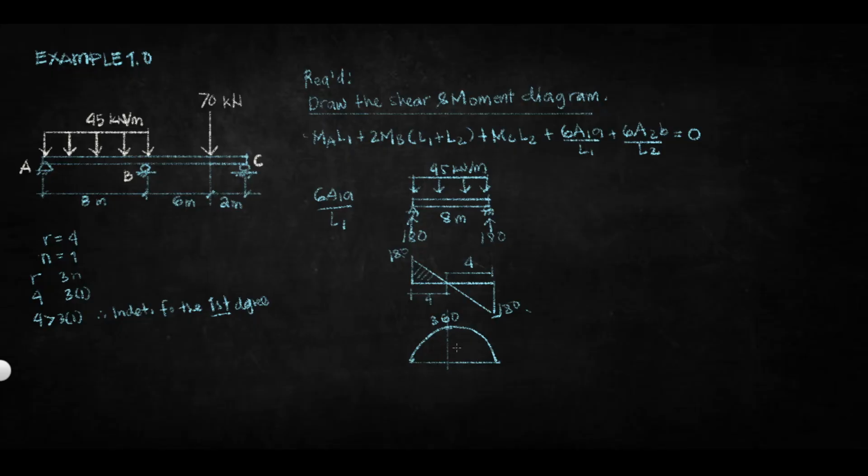to determine the centroid. So, ang centroid po nito, as we all know, na ay nasa gitna ng ating area of the parabola. So, this is, kung yung buong span is 8, kalahati nun, which is equal to 4. So, ang area nito, ng parabola is, class, 2/3 base, kasi nga parabola.